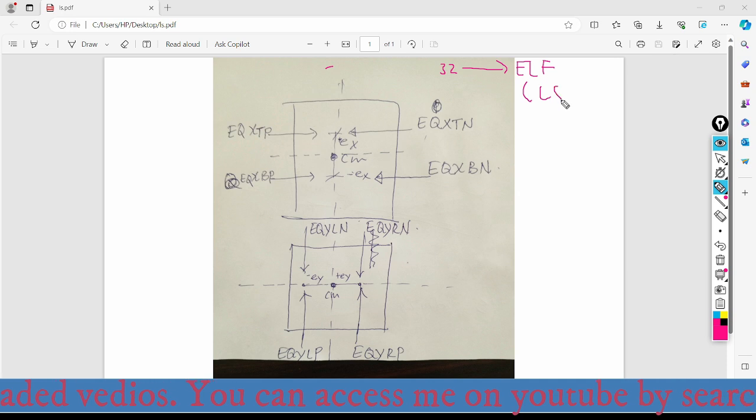That means for the linear static case they said that 32 combinations are required, and similarly 32 load combinations will be required for the response spectrum analysis. But this is the one which we need to correct while combining the load combinations, because they added an extra two load combinations